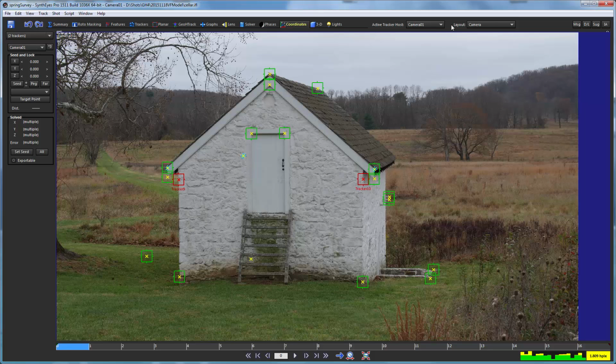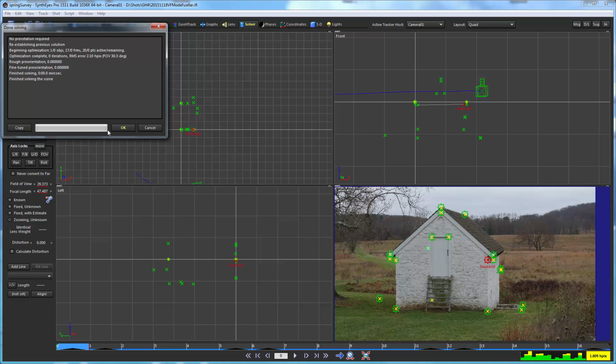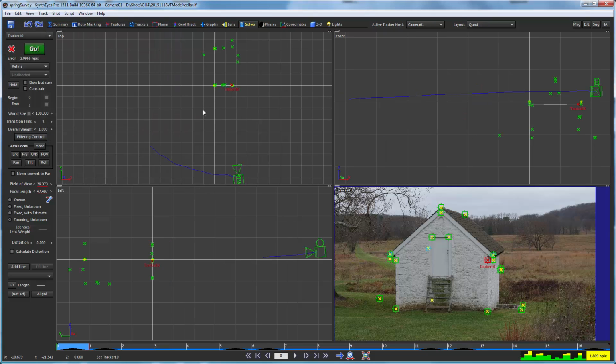It's basically we've told it that we want this one tracker to be on the x-axis, and it is, but it happens to be at an x of minus 15 instead of where we really like it to be, a plus 15. So what we can do about that is use these buttons up here, and we're just going to hit that once so that it shows x plus. We're saying that, hey, we want this guy to be a plus 15 instead. So now if I hit the solve again, it gets flipped back in the right direction.